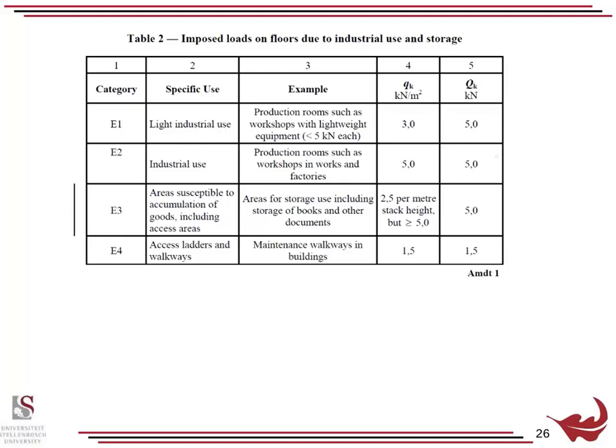And these rules often get broken. I mean, we had a client whose inaccessible roofs we designed for 5 kPa for that supposedly maximum load, because they have a big concrete flat roof in the warehouse, they might have this little room with a flat concrete roof on top, and then they get some new equipment.